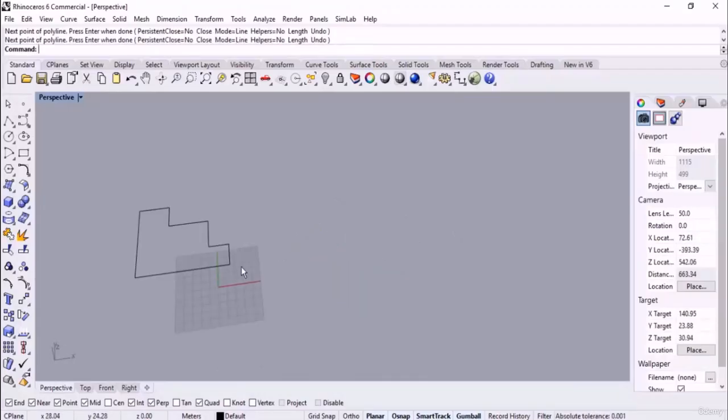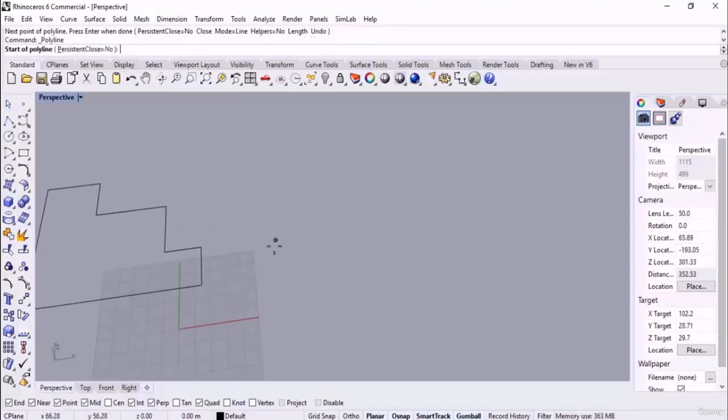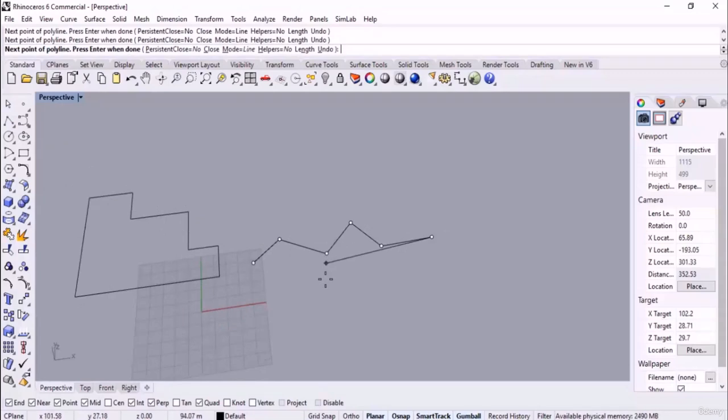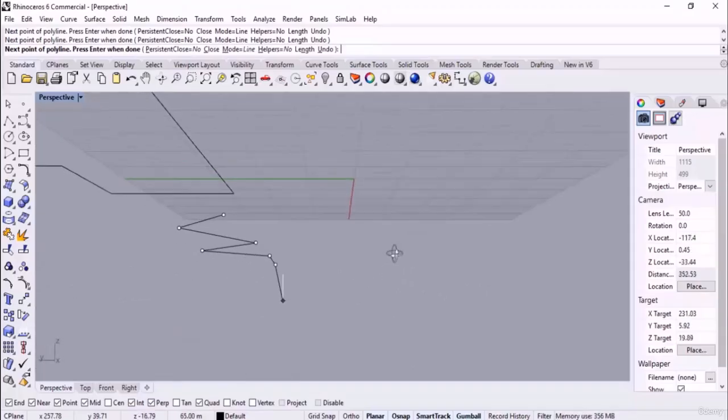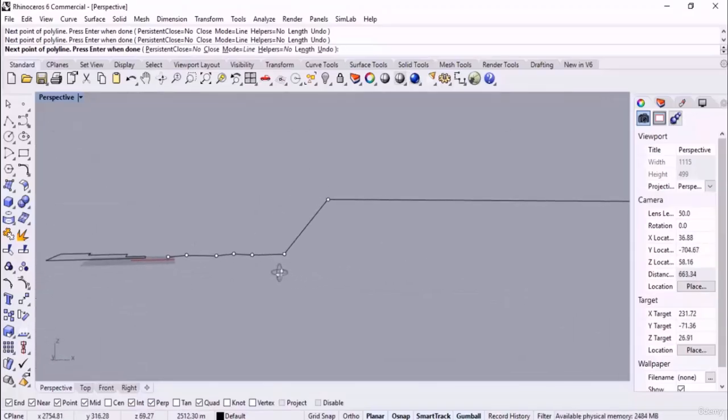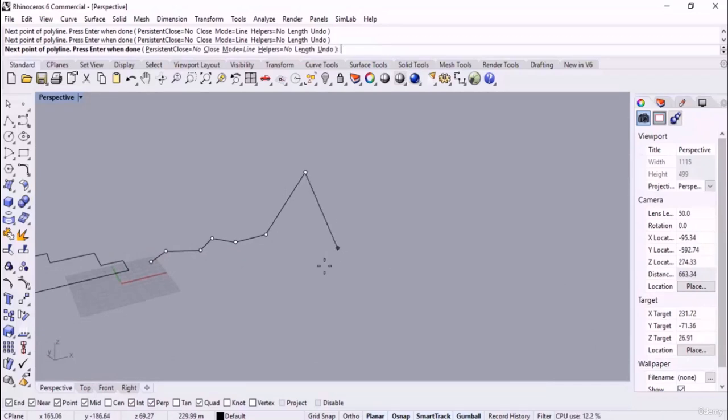And the next point is about the application of control button in sketching lines. Here if I pick polyline and then I start sketching by this way, specifying points, as you can see they are sketched on the plane. But here if I hold down control button, I haven't clicked yet, but I have held down control. Here if I click, then we can release control after clicking. Then if I move the marker of the mouse, as you can see, the point is perpendicular to the plane, to the specified plane that you have sketched the lines. Look in the perspective view.